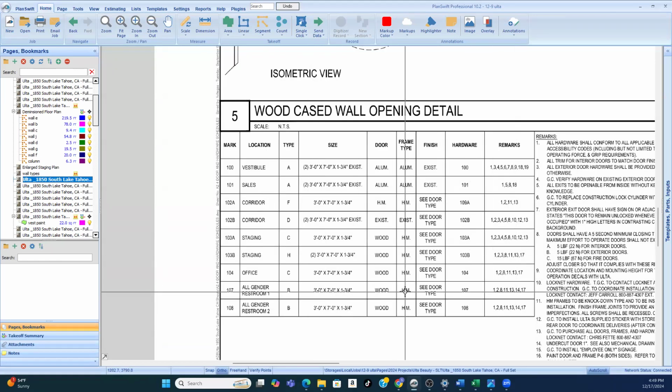So if I'm the framer, I'm framing the walls and I'm also doing all of the door frames. So I have to make sure I look at the framing for that and make sure I know if it's hollow metal or if we're doing wood framing. Hollow metal frames take a fraction of the time to install as opposed to wood framing. Hollow metal frames are like 0.9 of a man hour, where a wood frame is like 1.5 hours. So it's a real big difference when you're doing the frames.